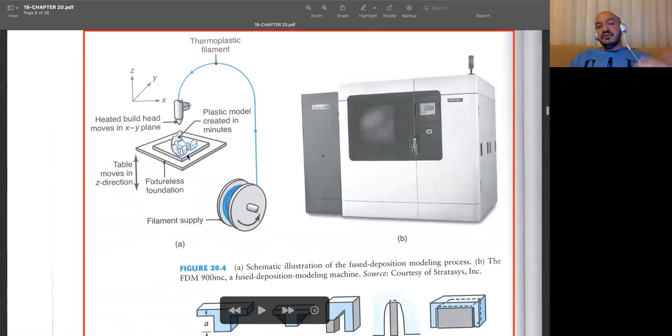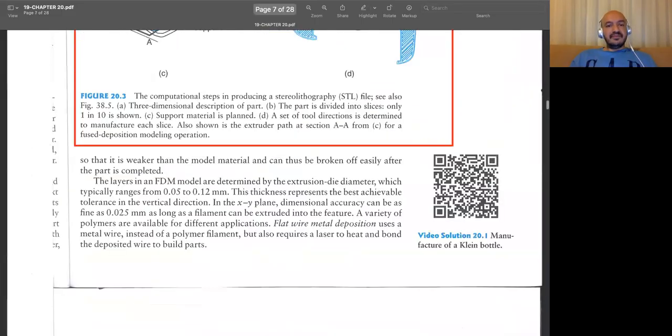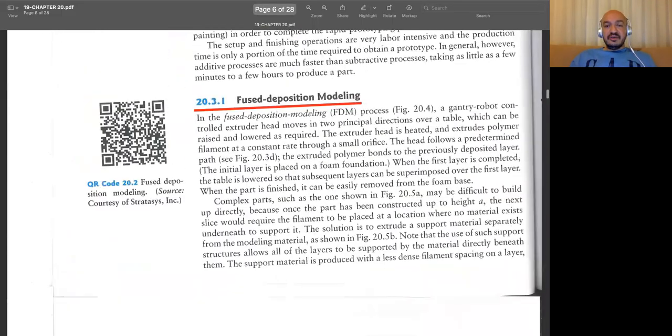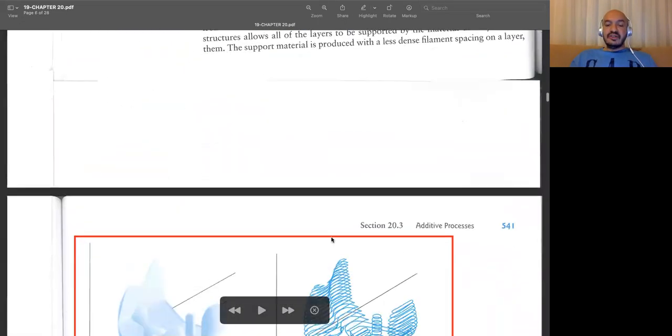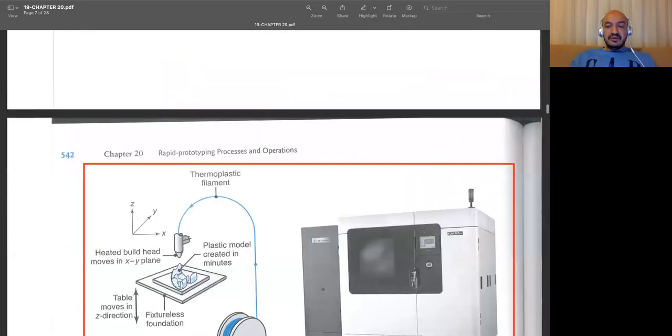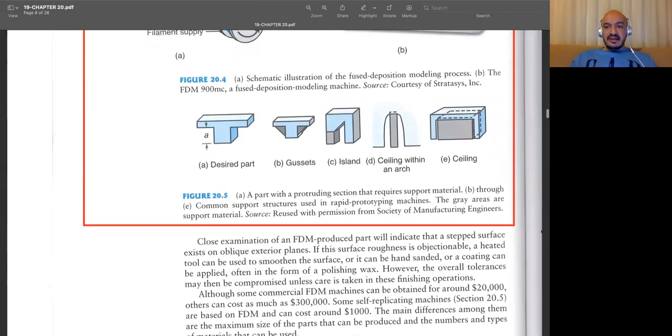Another thing is that for different types of materials, we may need to have a heated bed. For some specific plastic materials, the bed temperature is usually set to 60 degrees, 80 degrees, maybe sometimes to 100 degrees for difficult plastics, but usually it's set to 60 degrees for polylactic acid type of material. And as I said, I will be showing you the CAM software of this type of machines, and also I will make a demonstration on the machine. So I'm not going to spend more time on this.